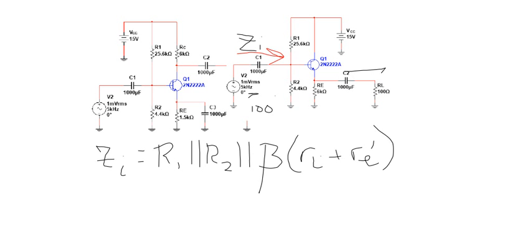But here, this will be my smallest one because this is going to be around 90 something plus a 25. I think that was 119 we just saw a minute ago. So the whole emitter circuit here is 119 ohms. But it gets multiplied times beta.